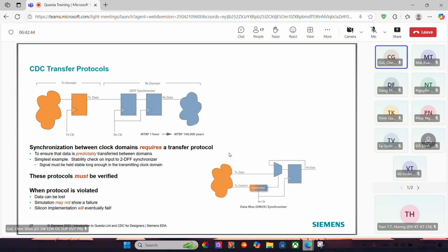So now we know about synchronizers. So we can ask ourselves whether we can just add this dual flip-flop synchronizer and be done with metastability and also the CDC issues. Simple answer is no, we cannot just rely on a dual flop synchronizer because dual flop is only helpful in certain situations. So for example, what if we have a 256-bit data bus? Then we'll have to add up to 512 flops to our design, which is not a very viable solution.